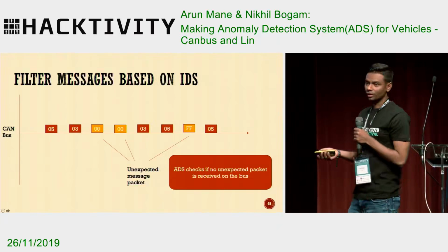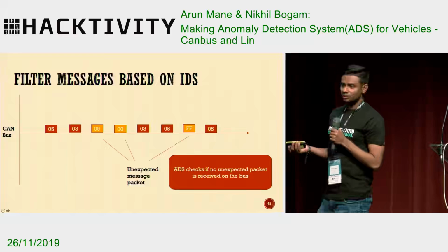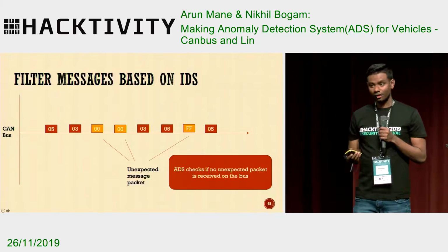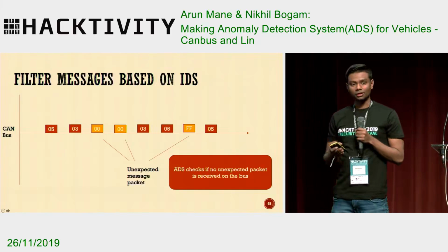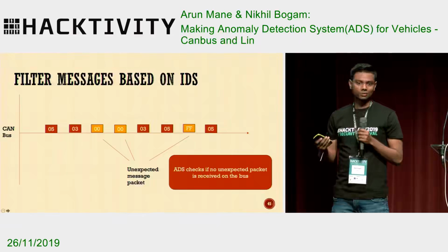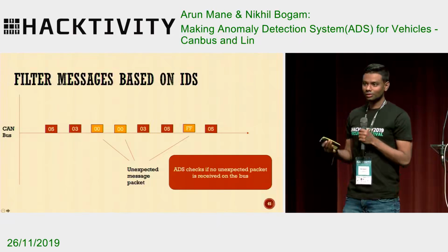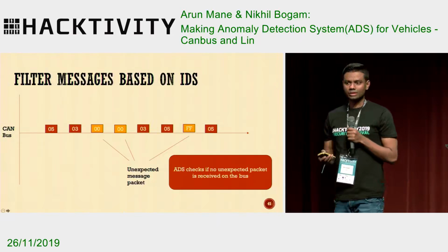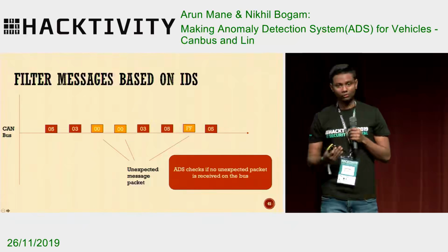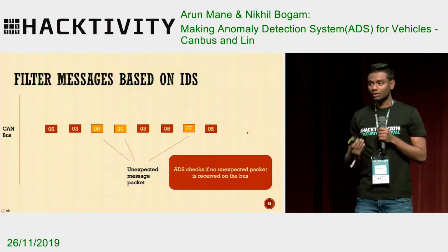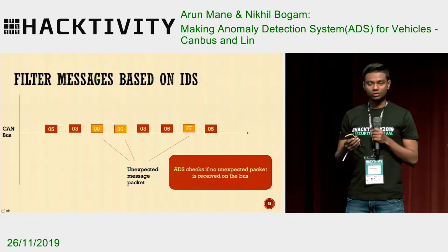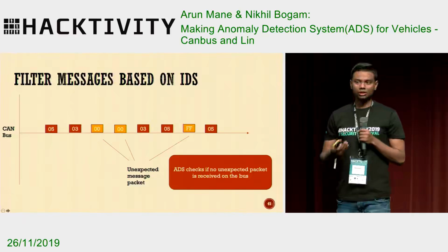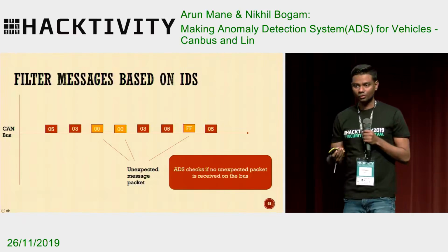One way is that you filter it out. If you check that, you will say, okay, we understood that this attack has occurred. What to do with that? A car is not like an IT system, where you have some warning system or something like this. You're driving at 200 km/h and your bus is not working, which is not a good idea. So automotive ECUs are embedded with software so that whenever something unusual happens, like the messages not coming, it goes into a safe state, which indirectly turns into a safe mode for the car.